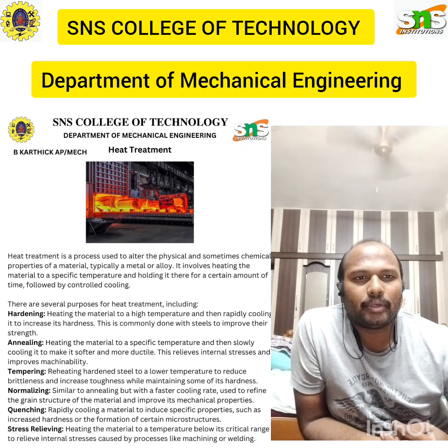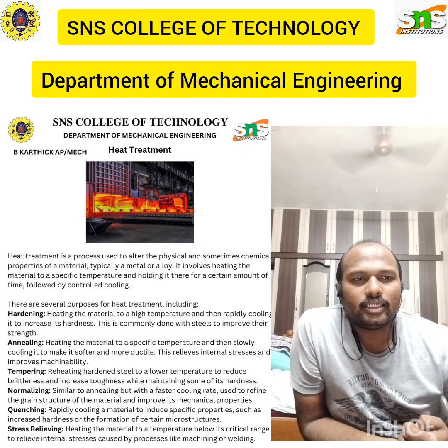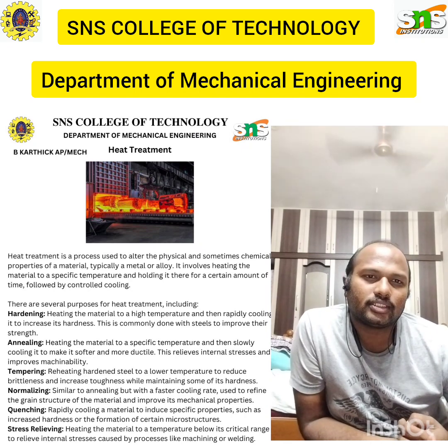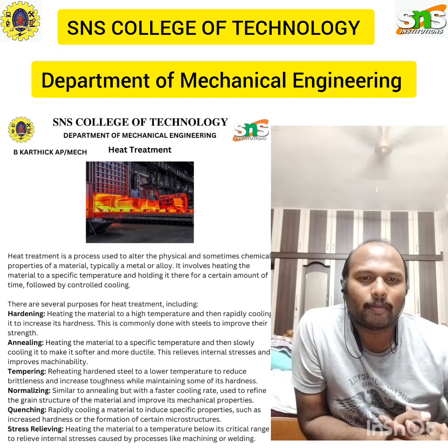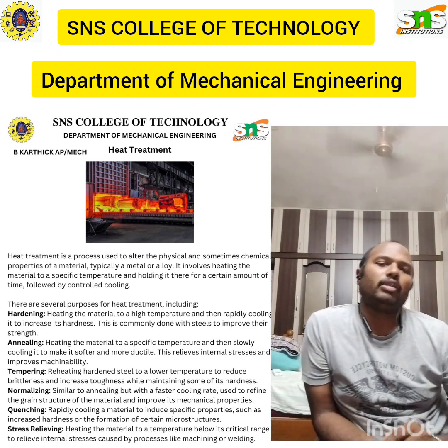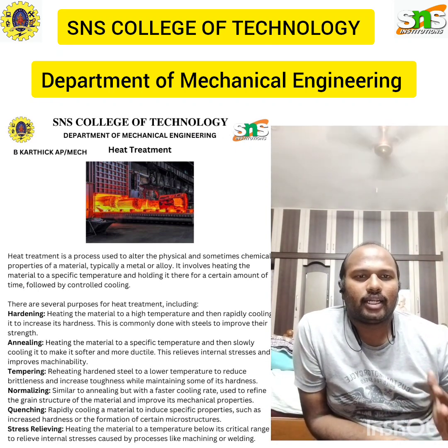And coming to tempering, reheating a previously hardened material to a lower temperature and then cooling it, which reduces the brittleness and internal stress while maintaining the hardness and strength. The tempering process is just like a twin for the hardening process. We never do the hardening process alone. Most probably we do hardening, and after the hardening, we will do tempering.